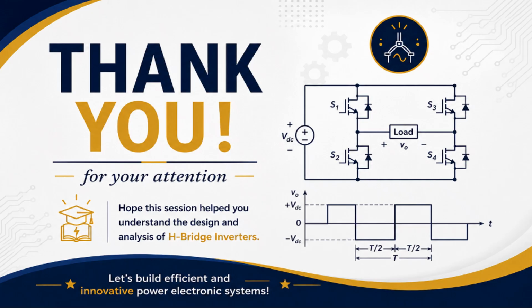Then unipolar PWM: two inverter legs are modulated separately. You will be having two separate reference signals. The output has three levels: plus VDC, 0, and minus VDC. We have also solved a design problem. We calculated the modulation index, switching duty ratios, switching time, motor inductance voltage, minimum inductance, and converter rating.